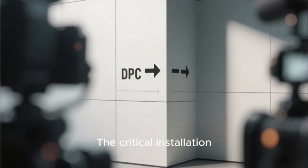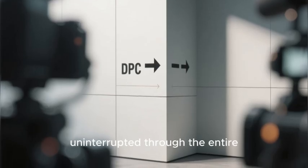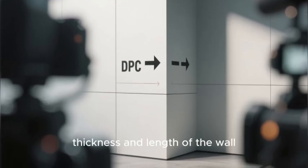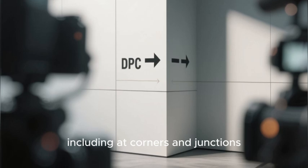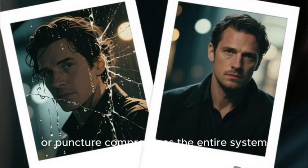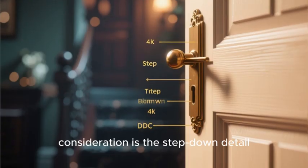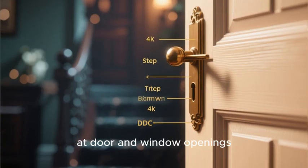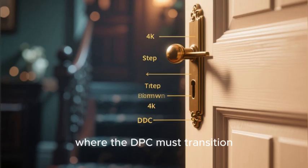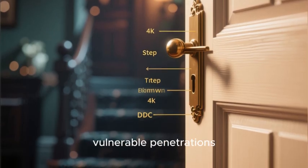The critical installation factor for DPCs is continuity. The barrier must run uninterrupted through the entire thickness and length of the wall, including at corners and junctions. Any break, tear, or puncture compromises the entire system. Another essential consideration is the step-down detail at door and window openings, where the DPC must transition downward to maintain protection around these vulnerable penetrations.